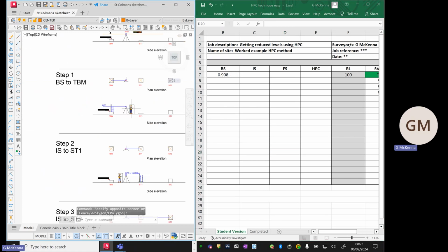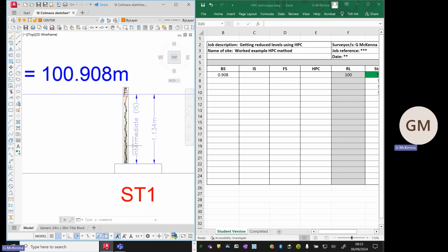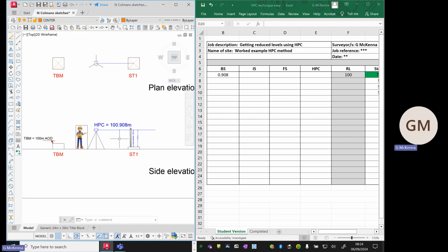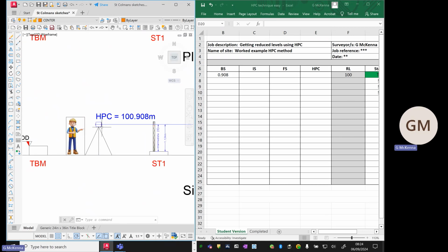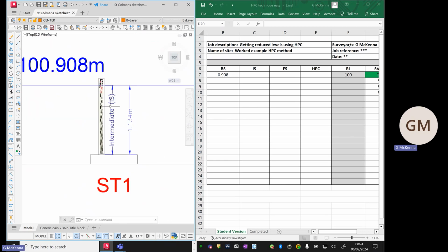Now, after you've done that, our second step is to work out the height to ST1. Unless we're going to change the position of the instrument, I could take 100 measurements with the level in its current position. Imagine you've set up your dumpy level in the middle of a basketball court, and you now know the height of that level. You could take dozens of measurements about the entire basketball court without having to move the dumpy level, and similarly on a soccer pitch or rugby pitch. All these intermediate measurements we're taking are referred to as intermediate sights, or IS.